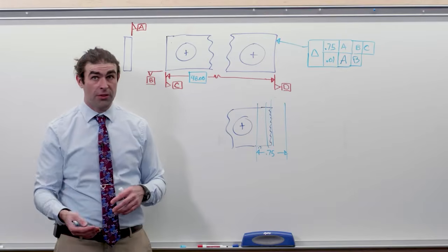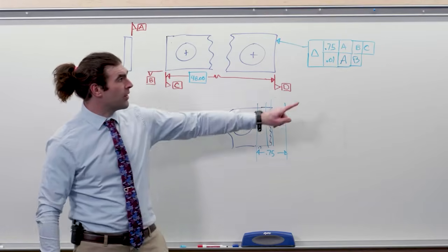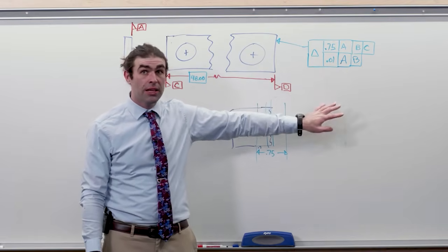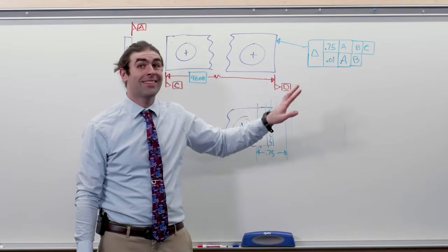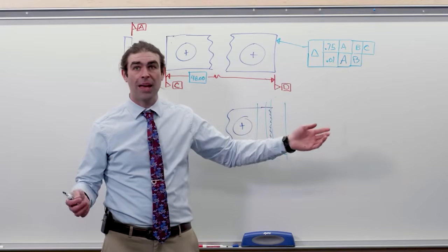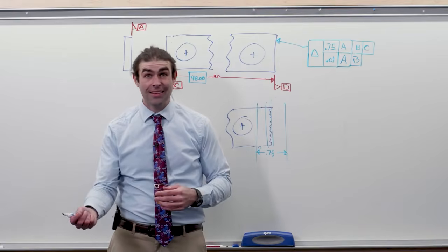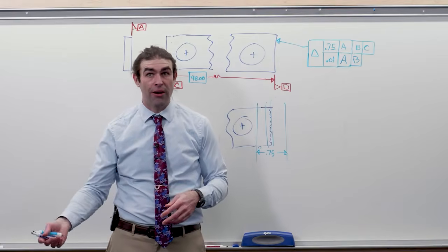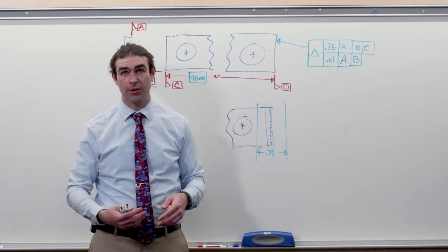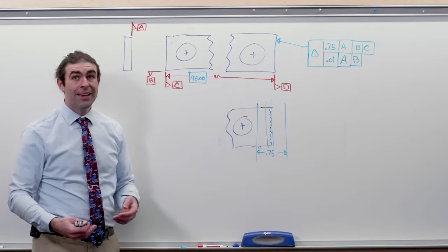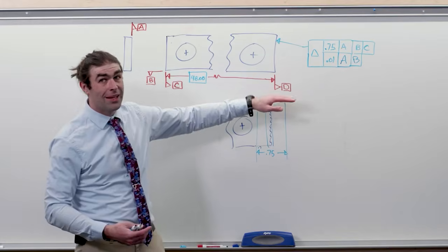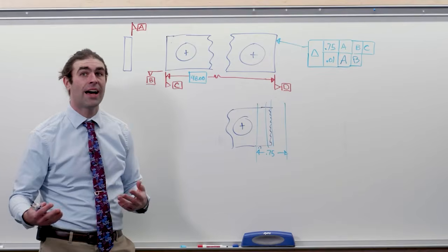Now, another thing I want you to take from this is that when you see a complicated feature control frame, it often means that you have more tolerance because the designer went through a little bit of trouble to figure out where to get some extra tolerance from. It's the easiest thing in the world to slap a profile of 10 thousandths to A, B, and C, or your primary, secondary, and tertiary datums on your part onto a drawing and it's normally good enough. But if you have this, it meant the designer went out of their way to find some tolerance.